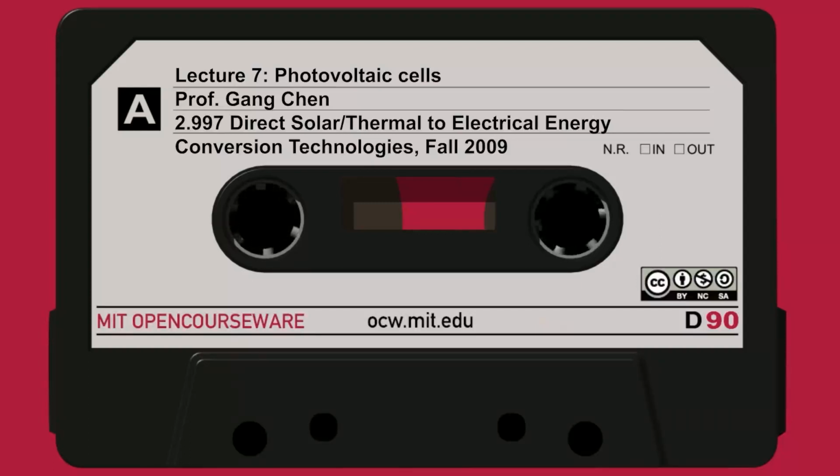And in the case of the PN junction, the saturation current includes the band gap and the diffusivity of holes. So on the P side it's really holes that carry the current. On the N side it is electrons, so diffusivity of electrons on the N side, diffusivity of holes on the P side. And then we have this one, the recombination time.